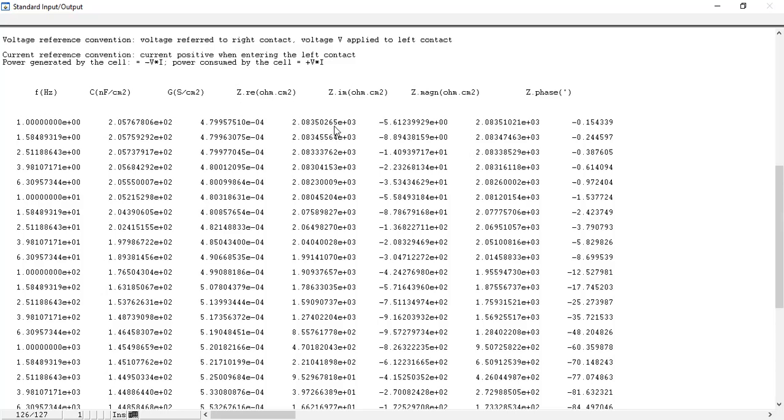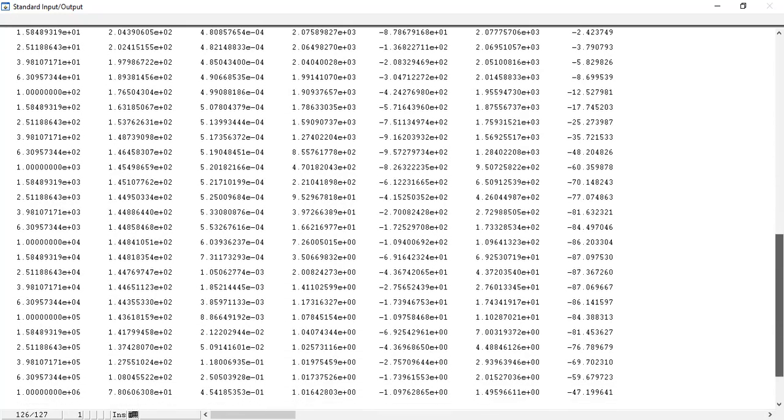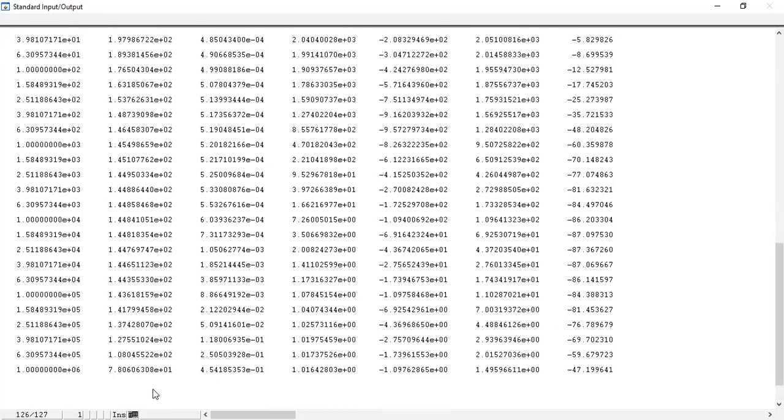we have higher impedance. We can see that we have higher impedance from over here. And then as we increase the input AC signal frequency, what is the impact on the impedance of my perovskite device? You can see that at 1 megahertz, we have a lower impedance, 1.01. It is about the lower value.